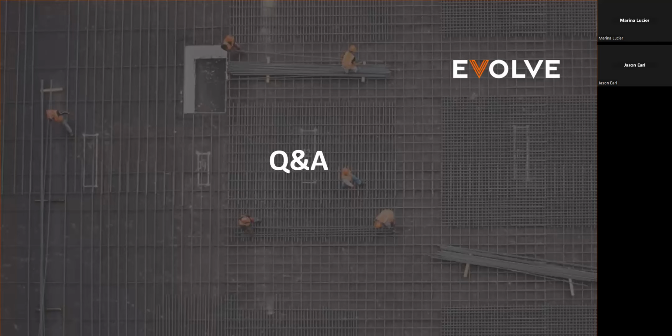All right, the next one here, are code blocks written with Python? You can write code blocks with Python. However, some code blocks are just created from other blocks. So you can create a custom block and you can essentially put a script into a block and have it be its own block. However, the more advanced method is to write them in C#. So you can create nodes the same way you would create plugins. And in Revit, that's done with C#.